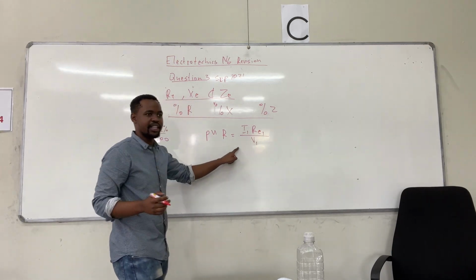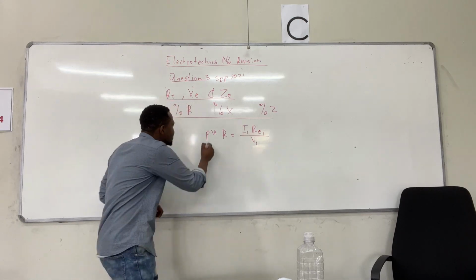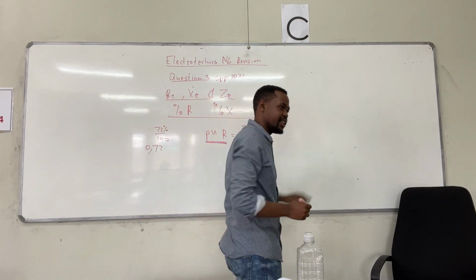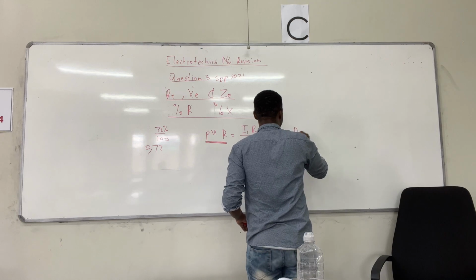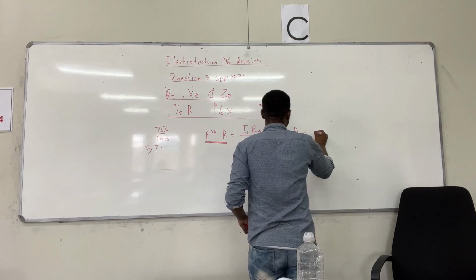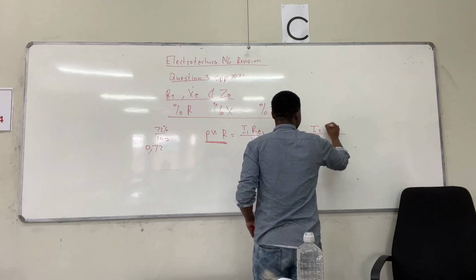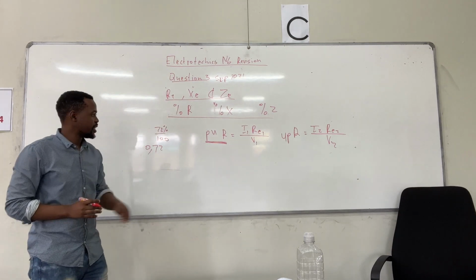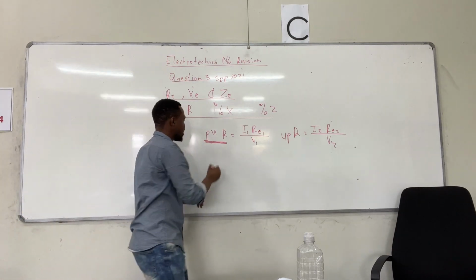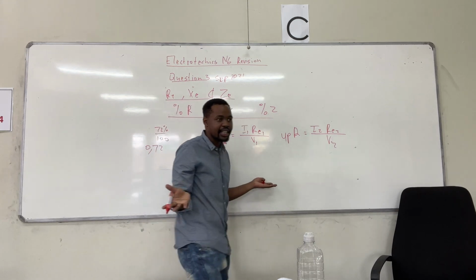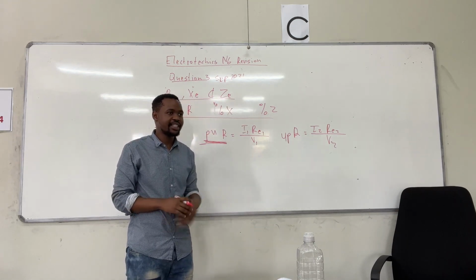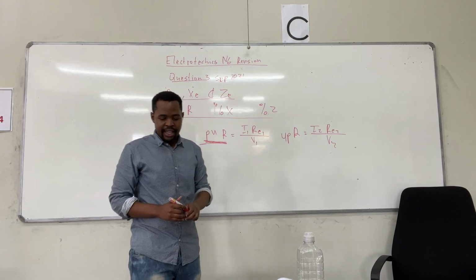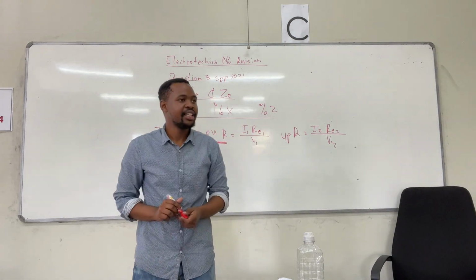If you wanted to calculate the equivalent resistance on the secondary side, you can still use the same per unit value. This value works on both primary and secondary. That is why the manufacturer gives us percentage or per unit values. The same goes for reactance and impedance.